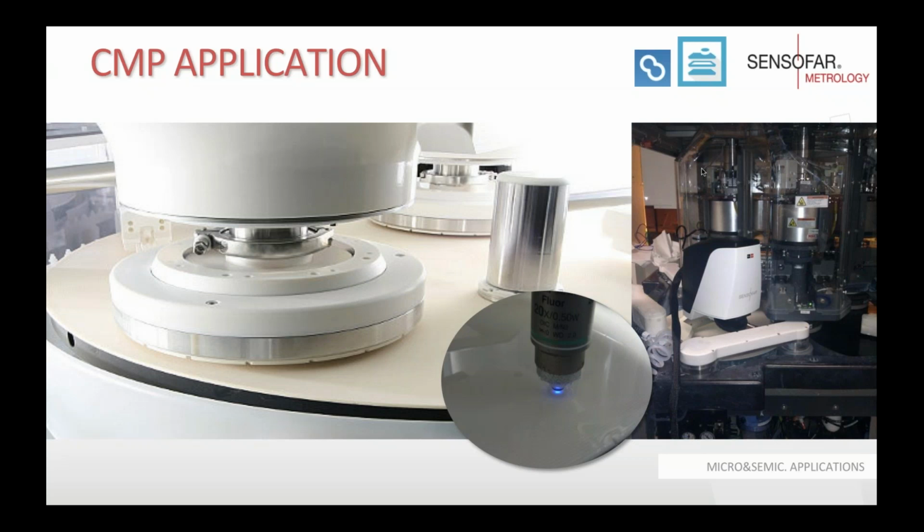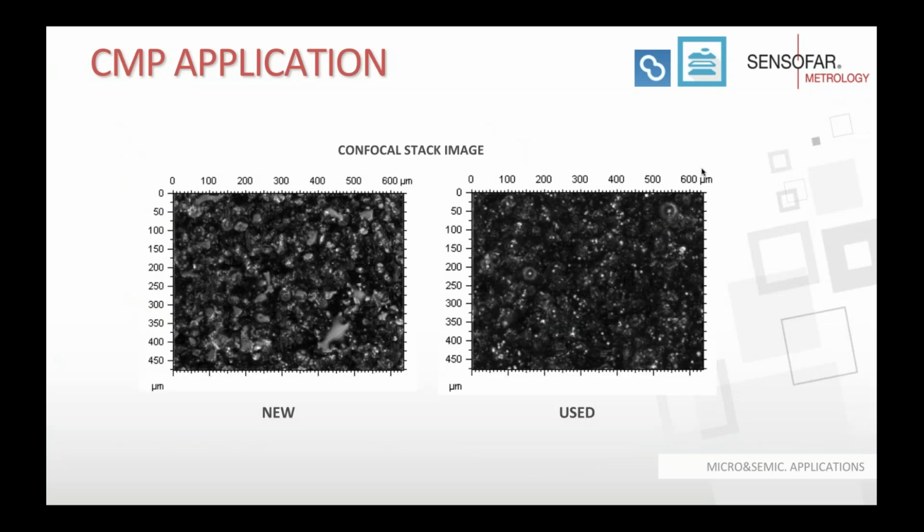So oftentimes vendors that sell the pads will mention that you get about 8 hours out of the pad. But we've been able to measure it in real time where we can extend the pad's life up to 28 to 30 hours. So this is a nice cost savings function by better understanding what the pad's surface is. And we achieve this by using a 100x water objective, or a 20x as well, is what you see in this image. Here's a quick example of a confocal Z-stacked image of the used compared to the new pad.